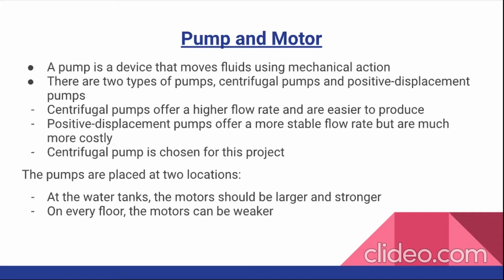This is mainly due to positive displacement pump being much more complex than centrifugal pump. Centrifugal pump has been chosen for this project because it is cheaper and the maintenance cost isn't very high. The pumps are placed at two locations, at the water tanks and on every floor of the apartment.